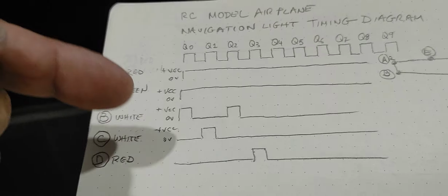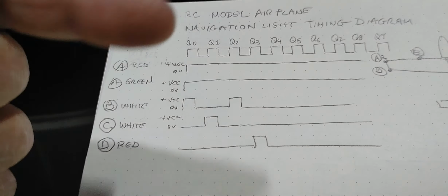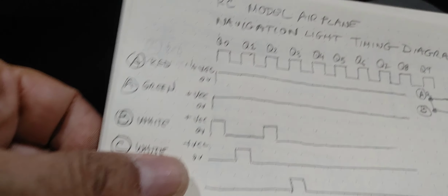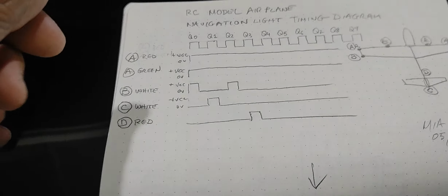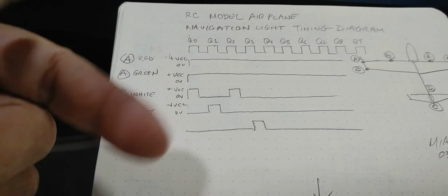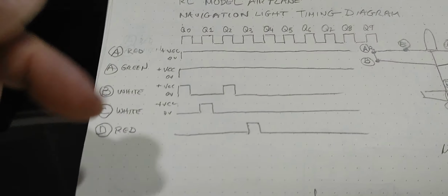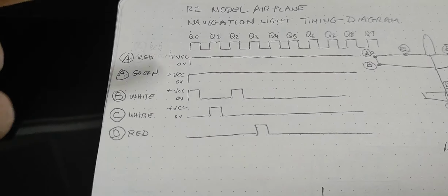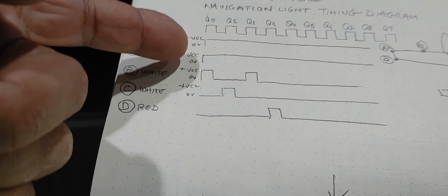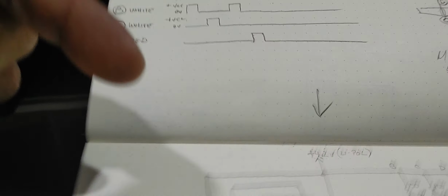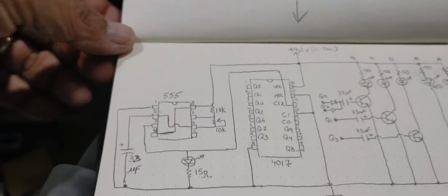And again, I have not seen anybody explain this. I wish somebody had explained this to people. I already knew this a while back, but I thought I'd do a video to explain this, because I've never seen a video of someone explaining this to this detail right here. And it's really simple. Once you understand what's going on here with the timing diagram, you can pretty much do any type of sequencing of lights using these components here, the 4017.